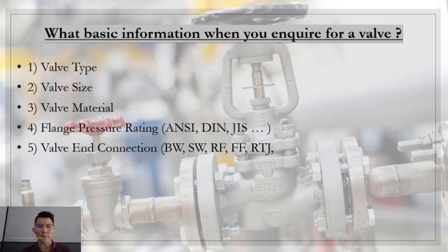And third is the valve material. On the material side, it involves a lot of parts, because for process valves, most of them use steel valves. Of course, we also have ceramic or PVC types. It depends on the compatibility, the so-called chemical compatibility to the process medium, to the medium you are using, the liquid or gas, or some acid, and so on. So how do we select the material on the body, on the bonnet, on the gasket, on the seat, on the seals, on the trim? These are all different, and we can select differently according to your process requirement.